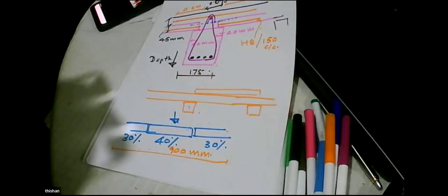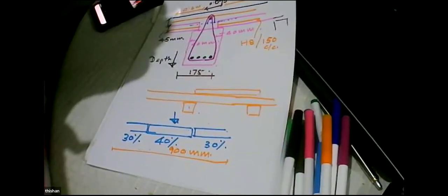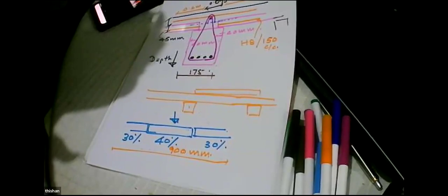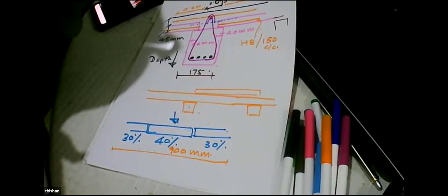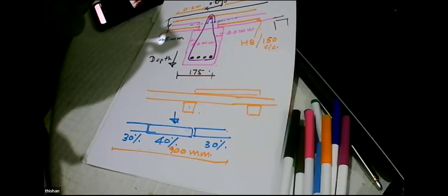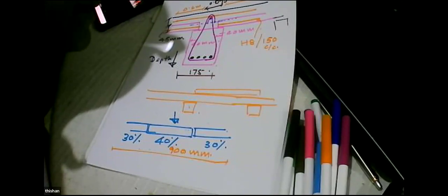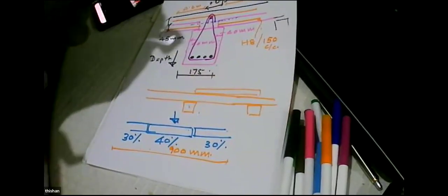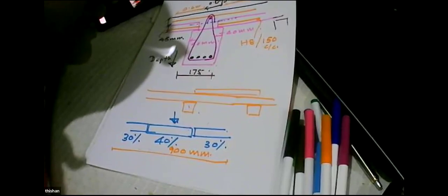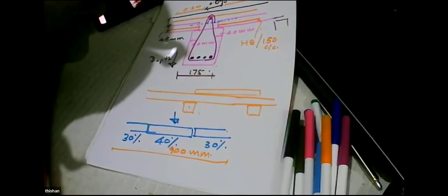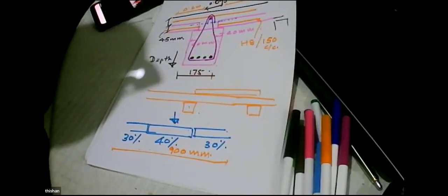When reducing the slab thickness, there are other concerns like fire rating requirement, heat transfer, and contamination. We don't have to worry about fire rating, because this is a slab, so half an hour fire rating is enough. Even if a slab has a local collapse, the whole building is not going to collapse. So what we need is about 30 minutes fire rating, and 30 minutes fire rating can be easily provided by these slabs. And if you have any issue with fire rating, then what you have to do is apply a seal. Sealing will look after that.